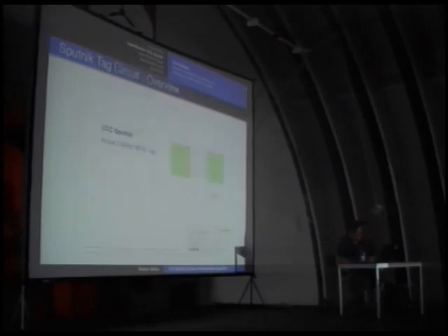These are the schematics. So the basic idea is that this is the top level sheet. On the top level sheet, you have these green boxes, and these green boxes indicate other sheets that are inside this. So if you want to get an overview, you look at the top sheet, and there you see basically you have 2 building blocks, a CPU and the RFB, it's a RF front end.